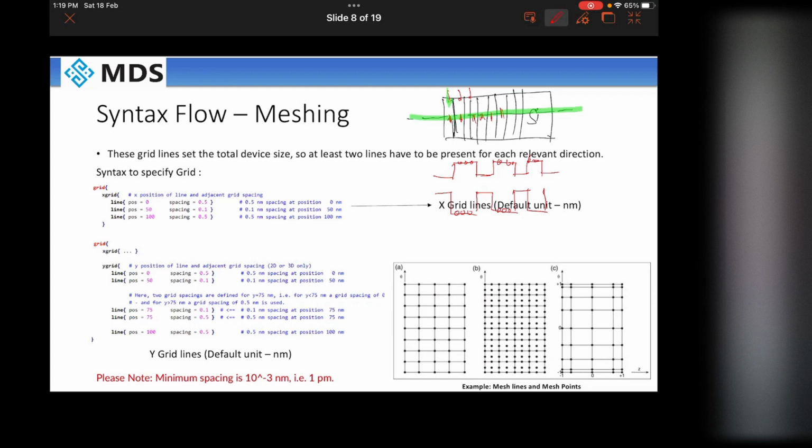What is the reason for that? The intersection of the layer. Yeah, exactly. This is our main part, right? That is how our barrier is changing. So here we should specify more, because if you specify fewer points near a junction, then it will move like this or like this, and your device functionality will change. You need to be more predictive, more accurate in this particular region,